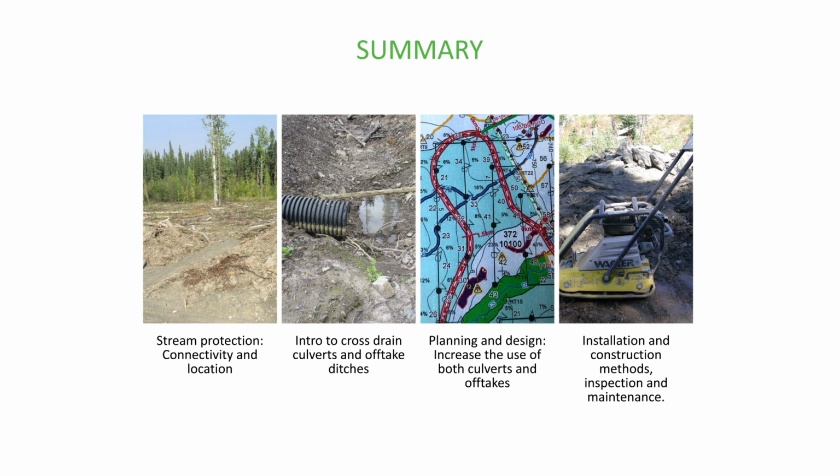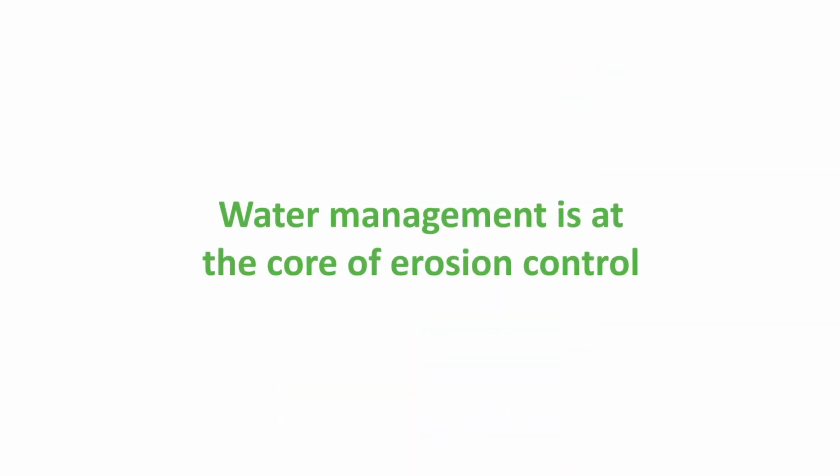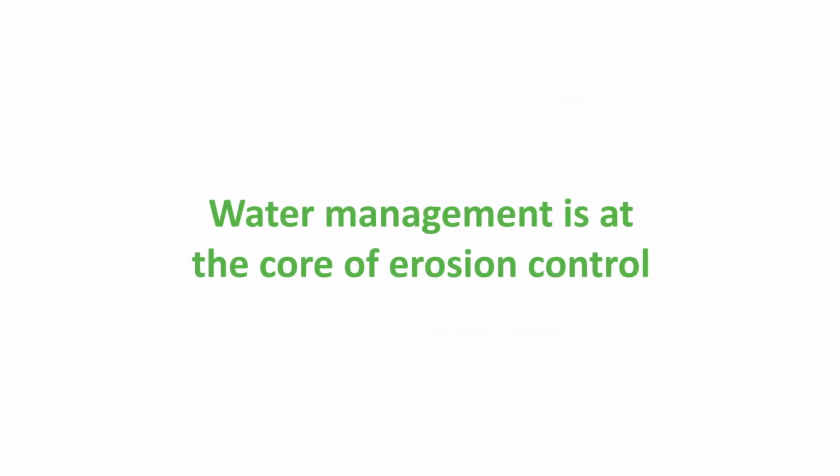While reducing the disturbed contributing area that feeds cross-drains is important, it should be noted that additional cross-drain culverts can reduce the volume of sediment transported from one culvert to many. Managing the water is at the core of erosion control.